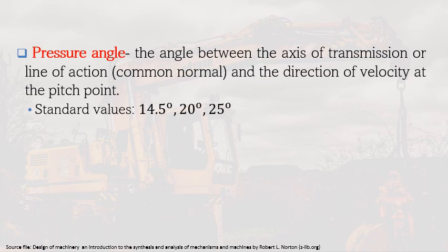Any custom pressure angle can be made, but it is expensive compared to the available stock gears, because stock gears are manufactured in these standard values. Custom pressure angles would be hard to justify. Special cutters would have to be made. Gears to be run together must also be cut to the same nominal pressure angle. So that's the disadvantage when you use angles other than the standard pressure angles.